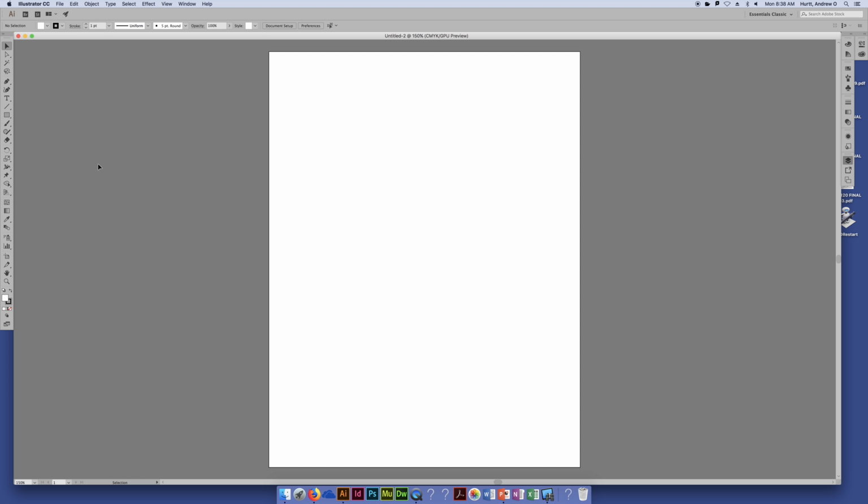Because generally I do my sketching, whatever you want to call it, on the sides usually, and I have copies of stuff that I played around with. And then I have my artboard where I have essentially my final stuff. And then when I export, you can check or uncheck use artboard, and basically it cuts anything off that's in the excess, so my clients never see the mess that's my workspace.